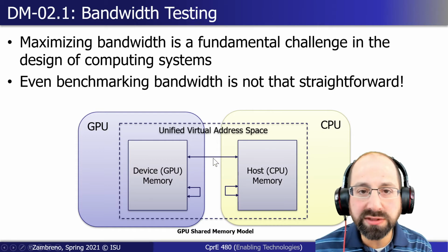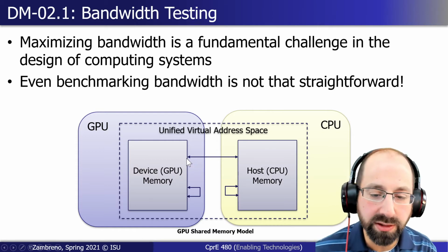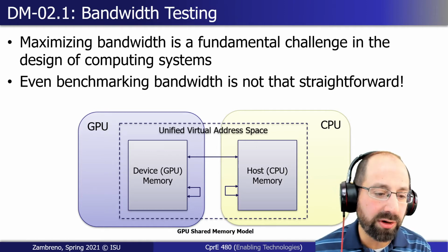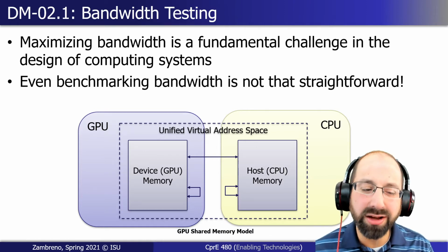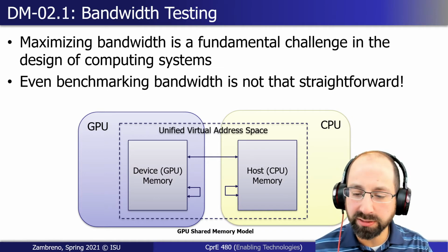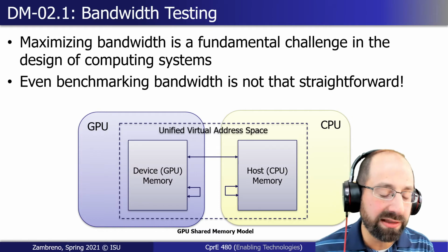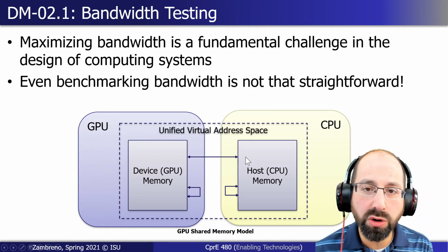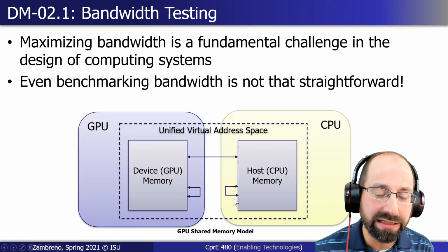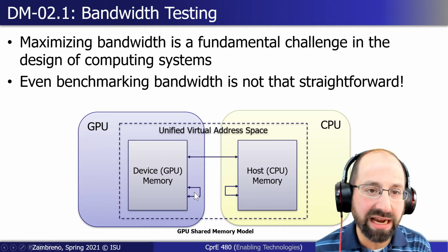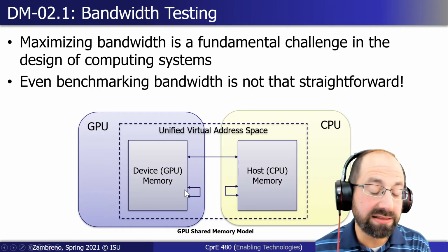But then you're also going to have those copies that go in either direction, from the CPU to the GPU or the GPU to the CPU. If you have a virtualized memory address space, there's underlying, I hate to call it hardware magic, but there's underlying hardware memory transfer engines that take care of doing that for you. But the cost is still there. GDDR has its own throughput associated with these internal copies, those little feedback arrows here, those device to device copies from within the CPU or on the GPU side over here. That is our DDR bandwidth.